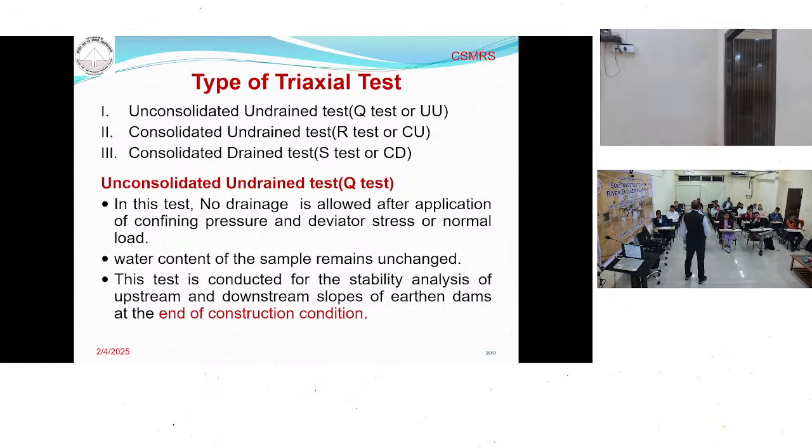So where do you require this test? In case of the embankment, in case of your dam, where do you require that test? Any guess? Tell me. You have constructed your embankment and you have used clay soil. Obviously, because the embankment is a water retaining structure, you are going to use clay soil. Clay soil has low permeability, so it will take time to dissipate all the pressure.